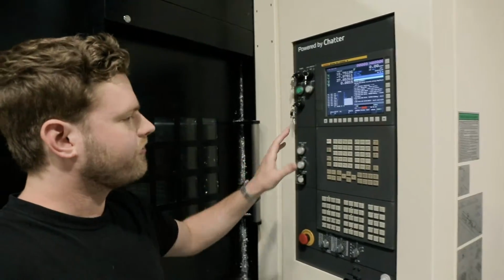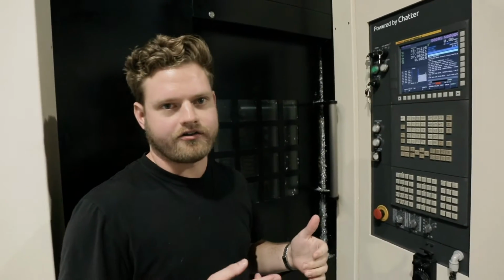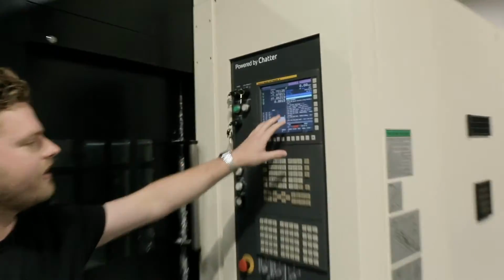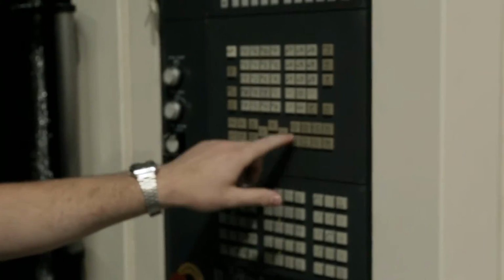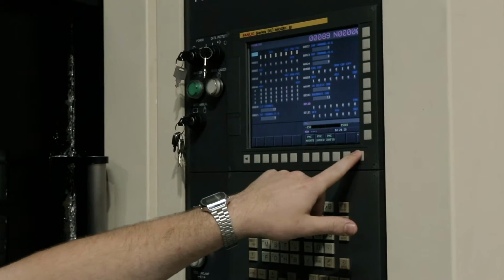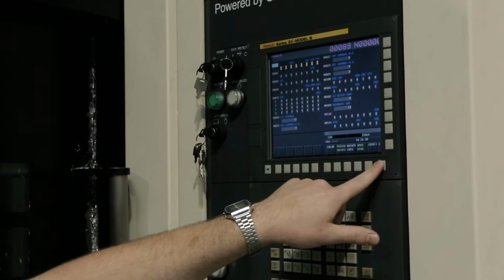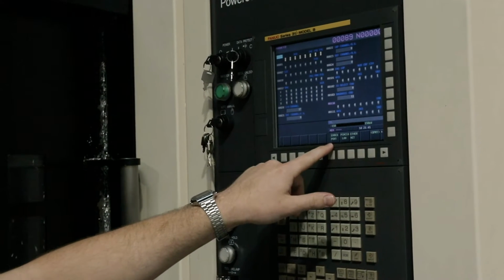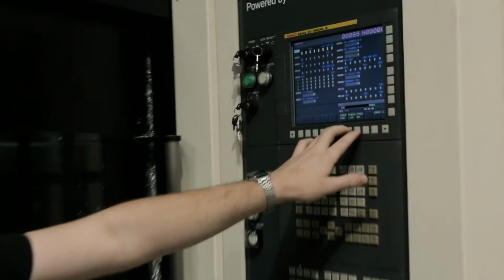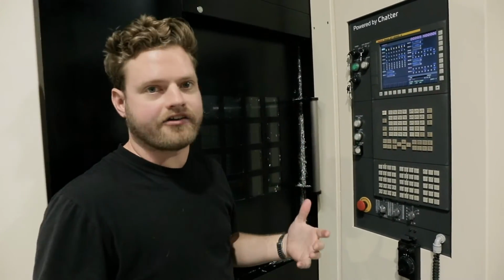So there's usually a couple network ports. There's either one or two. If you have a data server, there's the data server, and then there's usually the embedded Ethernet. So the way we see this is on the machine, we're gonna go to our system hard key, and then on these context buttons, we're gonna just press the plus until we get over to a menu where we see embed port, PCMCIA, and Ethernet. So these three are the three different interfaces that Fanuc has on this machine.